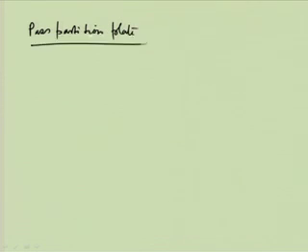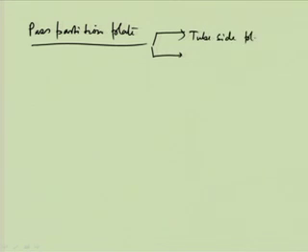So, this is very important. We can have a pass partition plate in the tube side, and we can have a pass partition plate for the shell side also. So, what are these? Tube side plate and shell side plate, and what is a pass partition?